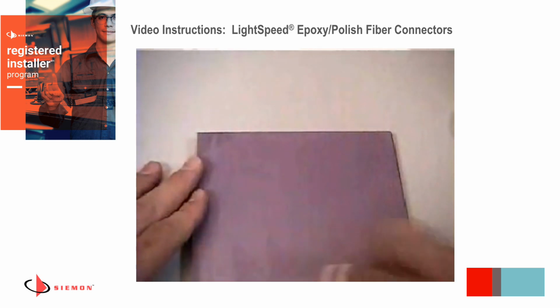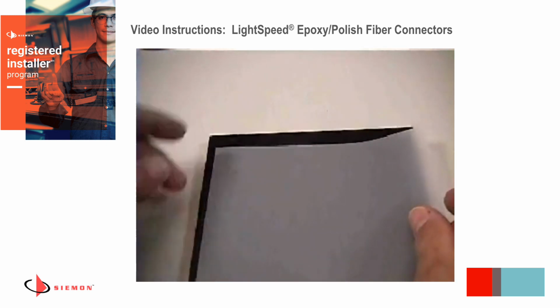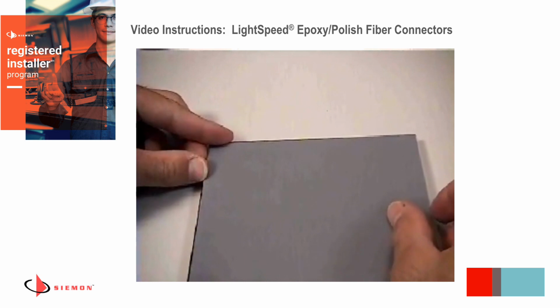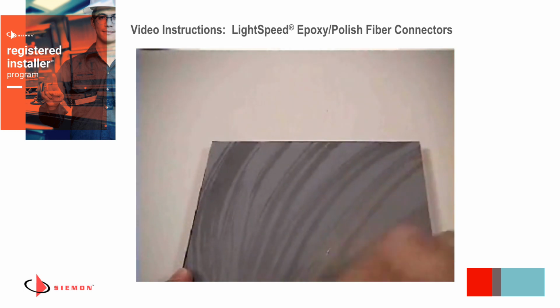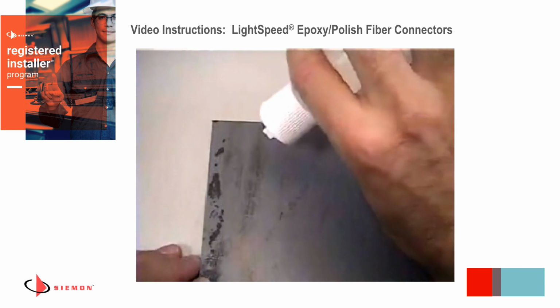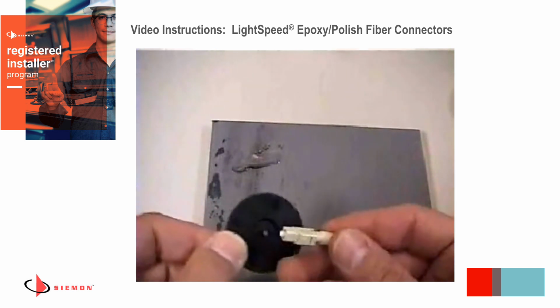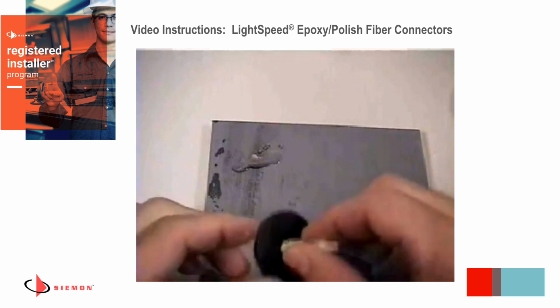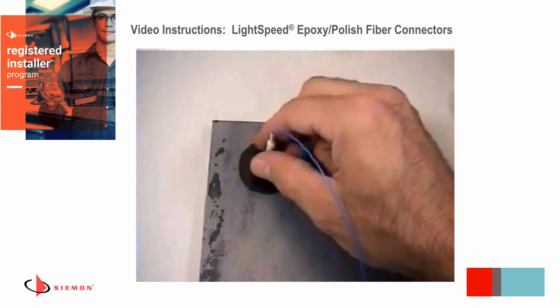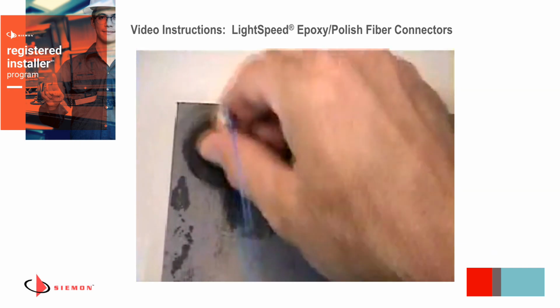The final polish with the white finishing film is required for single mode and recommended for multi-mode 50-micron connectors that are going to be used for high bandwidth laser optimized applications. Replace the purple film with the white finishing film and prepare as done previously with several drops of water. The finishing film differs from other films in that each section of this film can only be used one time. Choose an unused section of this film and continue polishing, but use light pressure for 25 to 35 cycles. Also limit the size of the figure 8s to 1.5 inches in height.